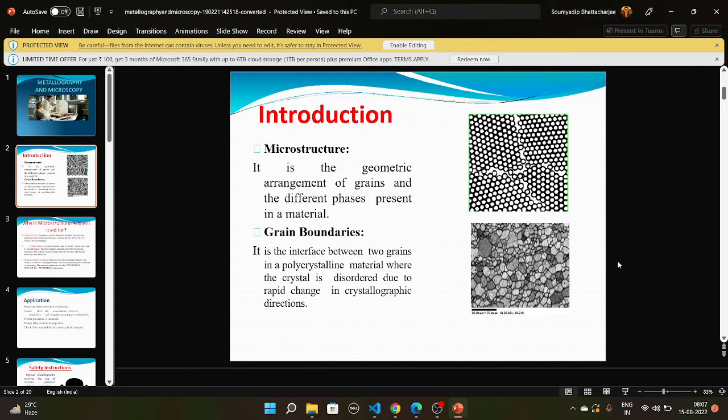So when the cutting force acts on the tip of the cutting tool, it is as if you are handling a cantilever with a point load at its free end. Can you imagine like this, Dipro? You have fitted a cutting tool over the tool post. You start machining, holding the job between two centers, and after proper positioning of the tool and the job. Now, when you start machining, some forces will be there. Out of the different forces, cutting force is maximum. The cutting force comes on the tip of the tool, and the tool is fixed at the other end. So it is like a cantilever subjected to a point load at the free end.